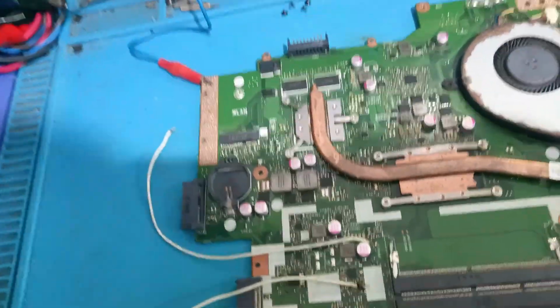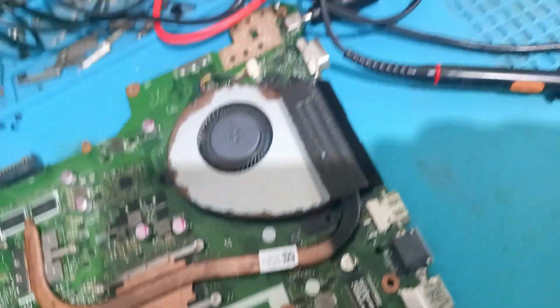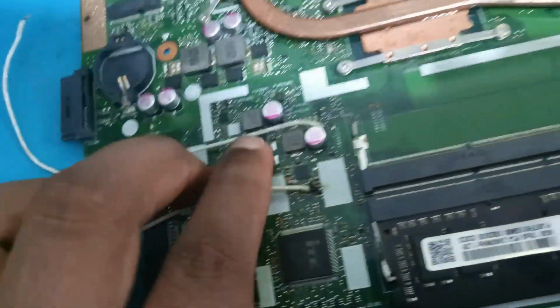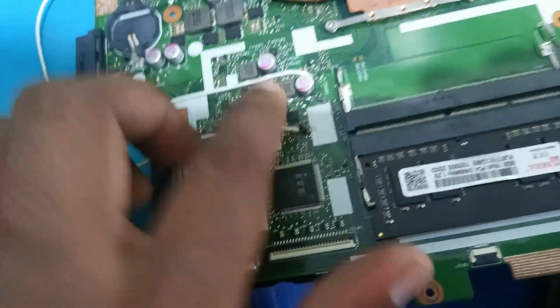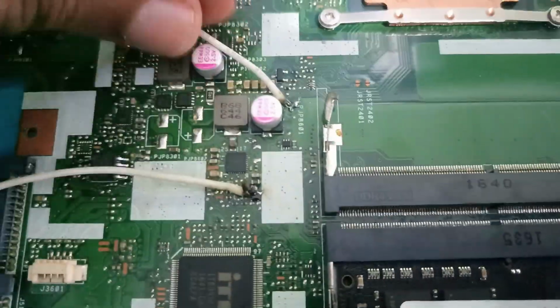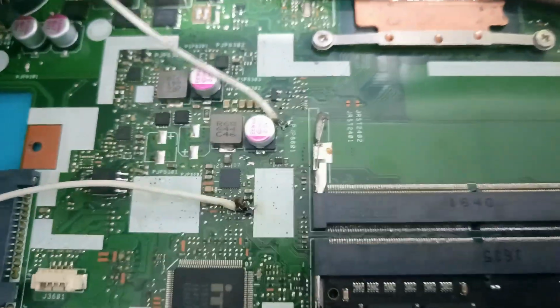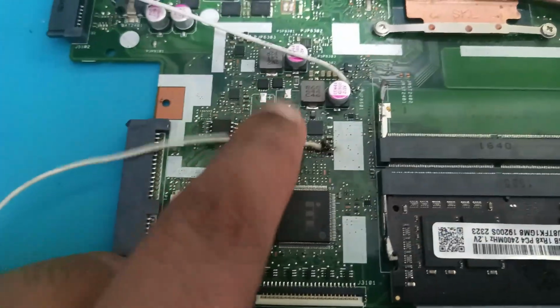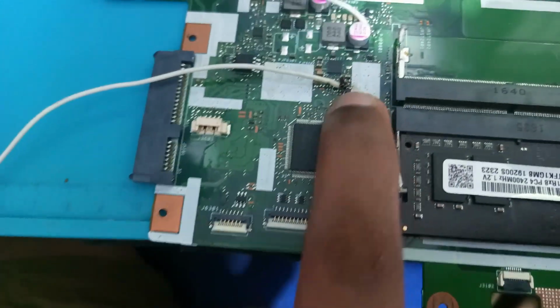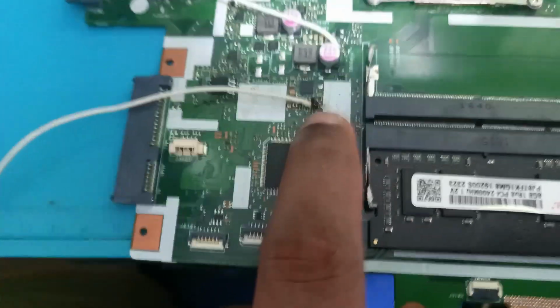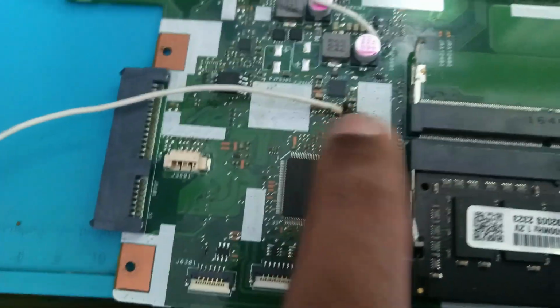Now our second lesson, how to capture SLPS signal with short circuit. Example, friend, this is a RAM coil. Okay, I soldered a wire to the RAM coil output. See this one, and this is the RAM IC. RAM IC enabling signal comes with SLP. I think this one SLP S5. I soldered the wire to the SLP S5 line.